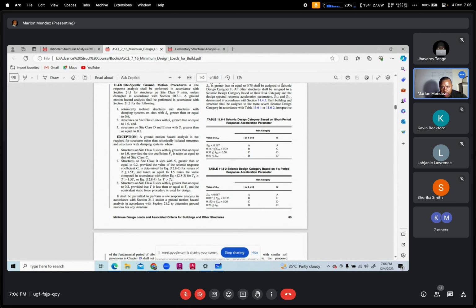What is important here is the risk category of the building. It's a hospital. The risk varies based on the level of occupancy and so on. I would expect a hotel to be more of a risk, category three, and your homes maybe risk one or two, based on the occupancy. You get this, right? You see the table? Yes, good.